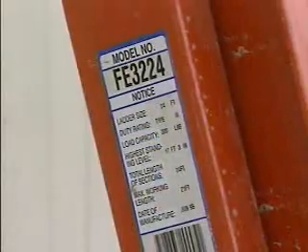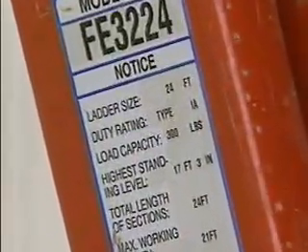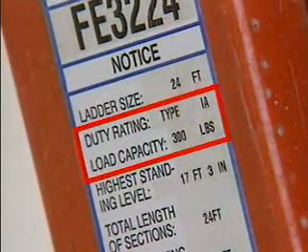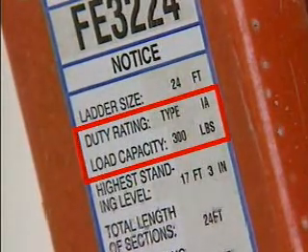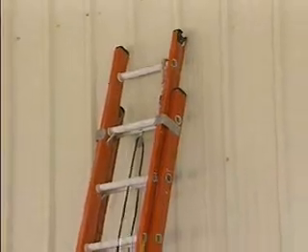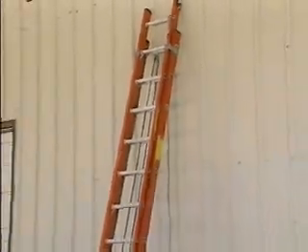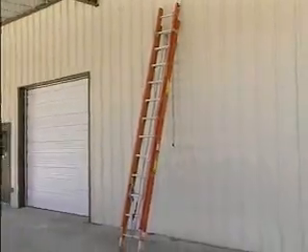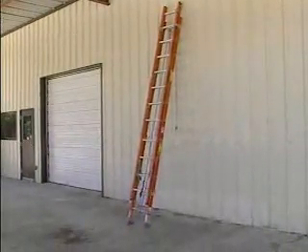Besides being available in different materials, ladders also vary in size and load-bearing capabilities. A standard rating system is used as the basis for dimensions and weight limits. The rating system classifies all portable ladders into one of four basic categories or types. One category is type 1A. Ladders in this category have a maximum load-bearing capacity of 300 pounds. Type 1A ladders are suitable for extra heavy-duty applications, such as those found in industry, utilities, contracting, and so forth.